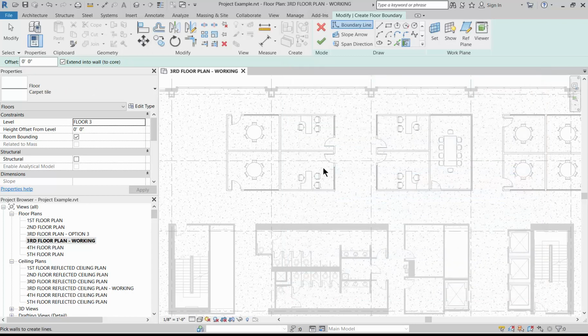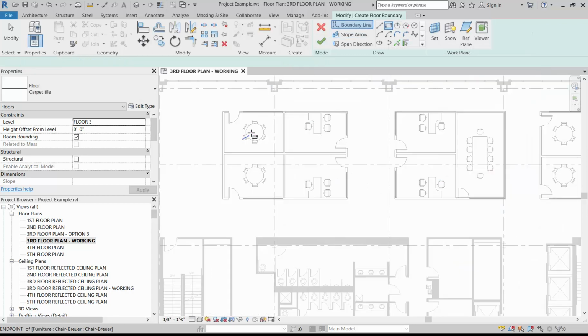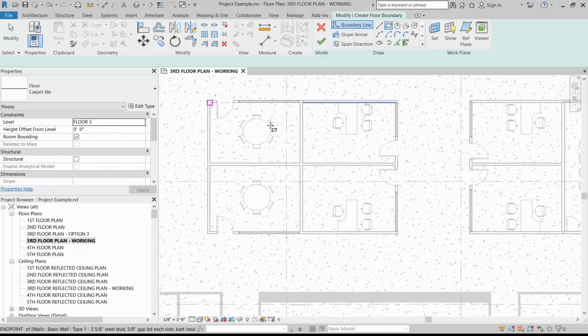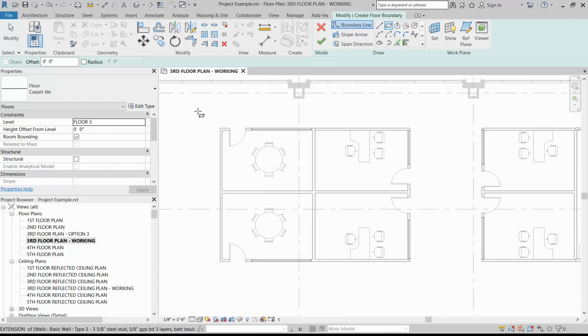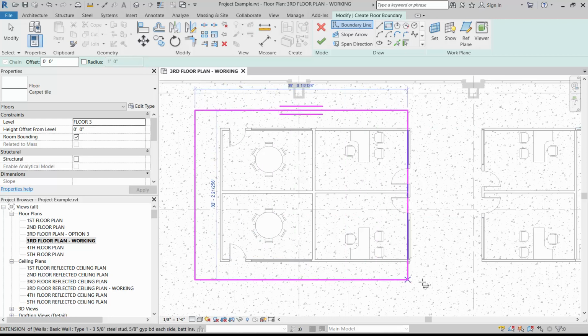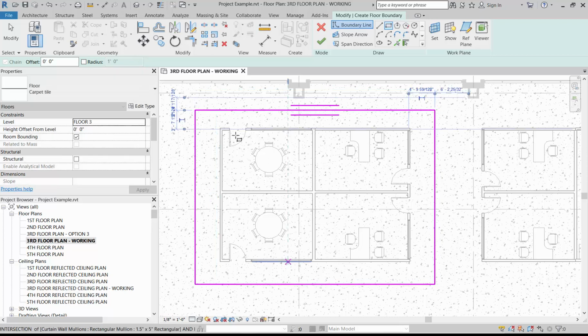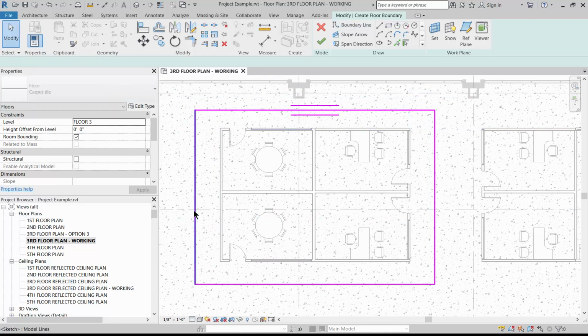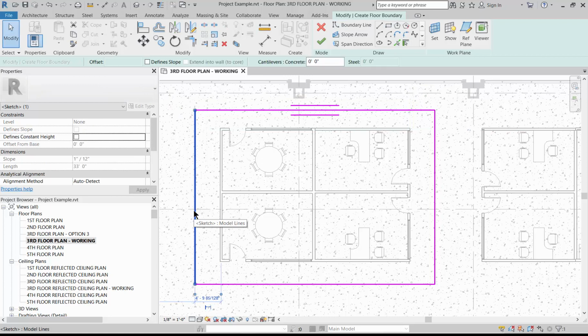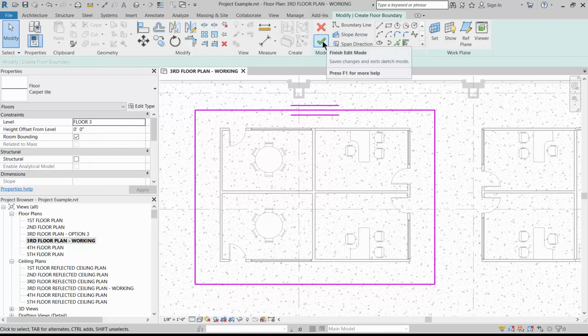Okay, so I have my structure defined, and now I actually need to draw the carpet. So oftentimes carpet is going to be within the room. You can sometimes get a special effect by actually running it slightly outside for the circulation area. So let's show what that might look like. So we could actually have a carpet that covers a little bit of circulation area, so as you're approaching the room you have some of it on the outside, and it looks like about 5 feet from the wall, so 4 feet to 5 feet, good for a circulation pattern.